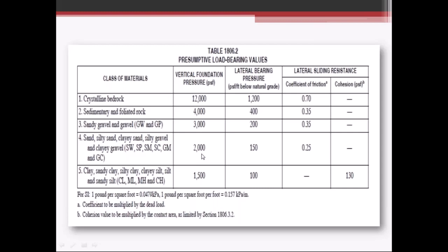It's been my experience that the bearing pressures are generally conservative in this table, so doing some additional lab testing can usually increase those values for foundation design.